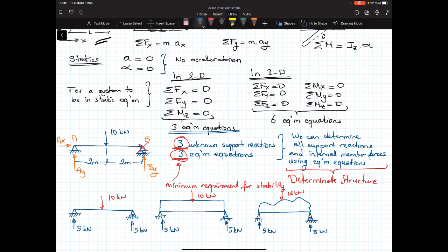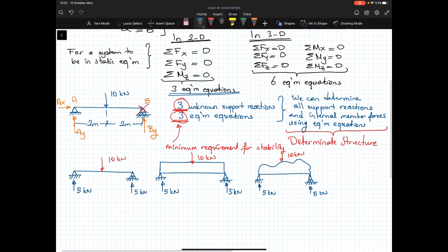right? The same internal forces, because the force distribution depends on equilibrium equations, these 3 equations, nothing else. And if you look at these equations, we don't have the sectional properties. We don't have the material properties in these equations. So actually, the force distribution or the support reactions is determined by these 3 equilibrium equations.